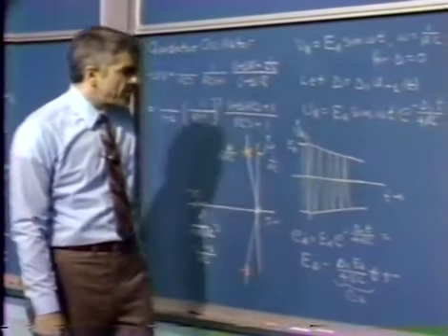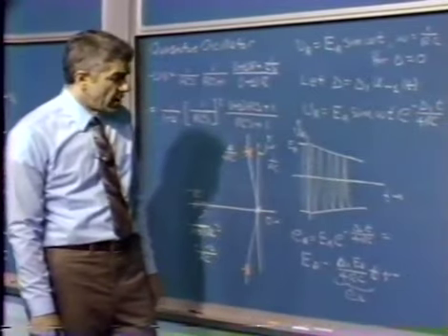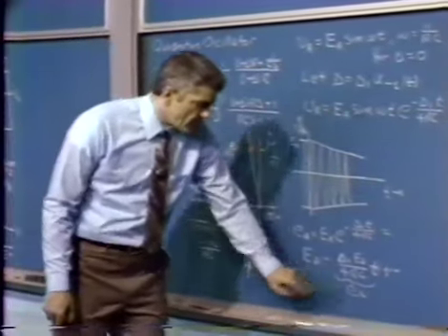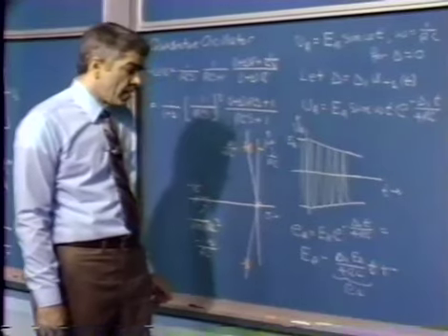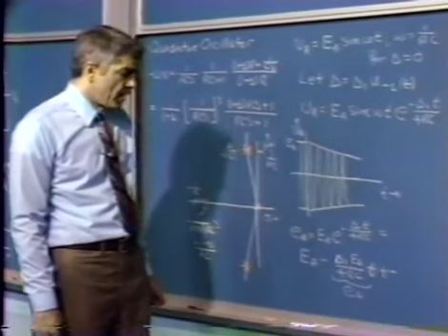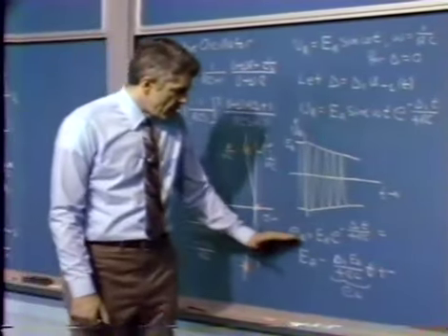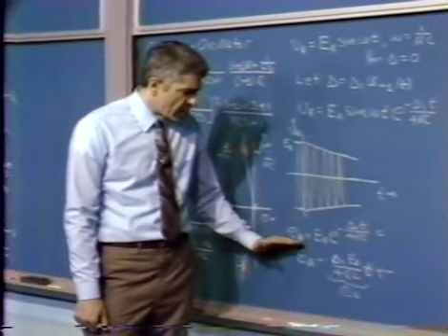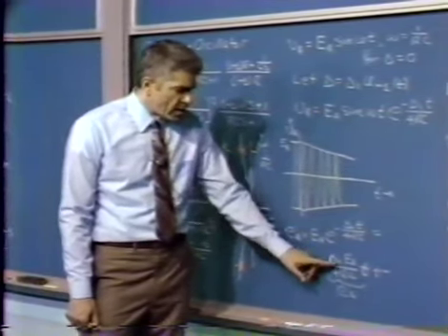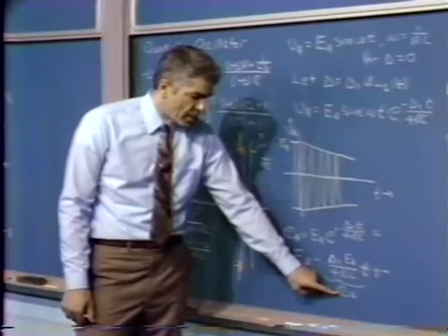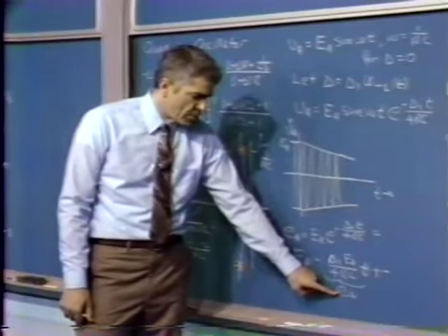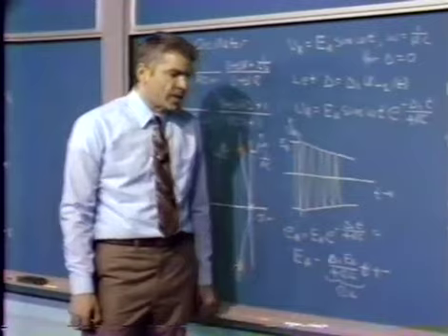What we find is that we make a step change in delta, and when we draw an incremental or linearized block diagram, in response to a step change in delta, we get a negative ramp for the incremental change in the envelope. E sub a is something times t.